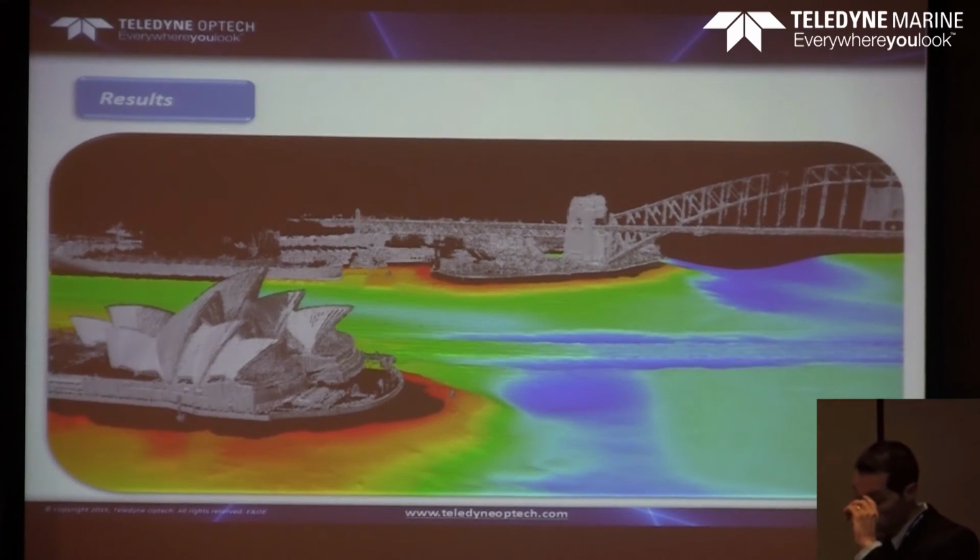Now, the result was actually amazing. We got basically the whole rock, so all the harbour. What you can see, and something that I didn't mention before, is that you always see a little bit of gap between the laser scanner and the bathymetry data. In this case, we used, if I'm not wrong, the Seabed P50, so the aperture is 165 degrees. So whenever you do the bathymetry, you just miss some data set on top.